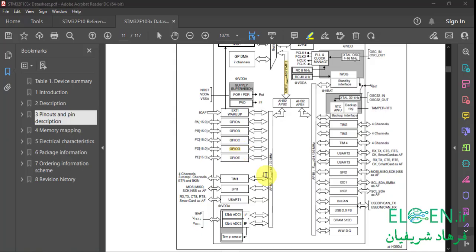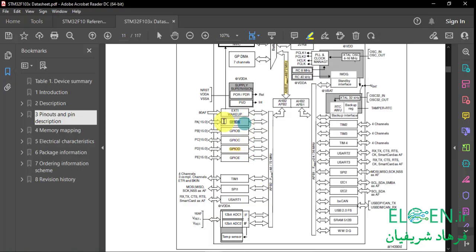Peripherals are electrical circuits designed to do specific tasks, which is mostly about sending or receiving some form of data. This data could be of type Boolean, like the state of a GPIO pin. For example, configuring pins in input or output mode, changing pin state in output mode, or reading pin state in input mode is done through GPIO peripherals. Each GPIO peripheral can control up to 16 pins. So how can we tell a peripheral what we want to do?